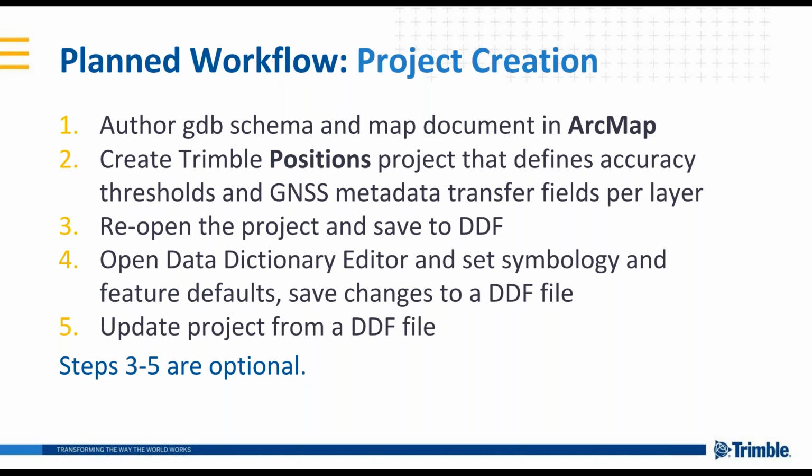You then, at that point, would reopen the project and save it out to a DDF, okay? So there's a screen for this. And you can then take that DDF right out to the field and start doing work in it. If you're not interested in checking out existing data, if you want to just do new data collection, you also have the option of opening up that DDF in Data Dictionary Editor, setting symbology, setting feature defaults, making other changes that are specific to TerraSync logging options, things like that, and then saving those changes to the DDF file.